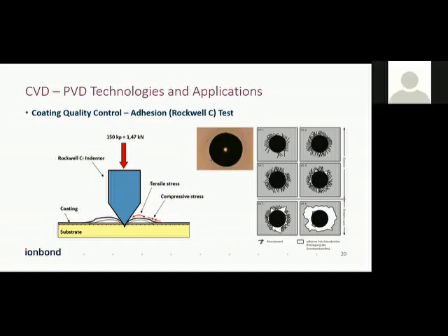So are you referring to vacuum impregnation? No. Some kind of degassing, we carry out one or two processes so that whatever debris or foreign particles are there in the porosity, we take out first, and then carry out the coating on that.